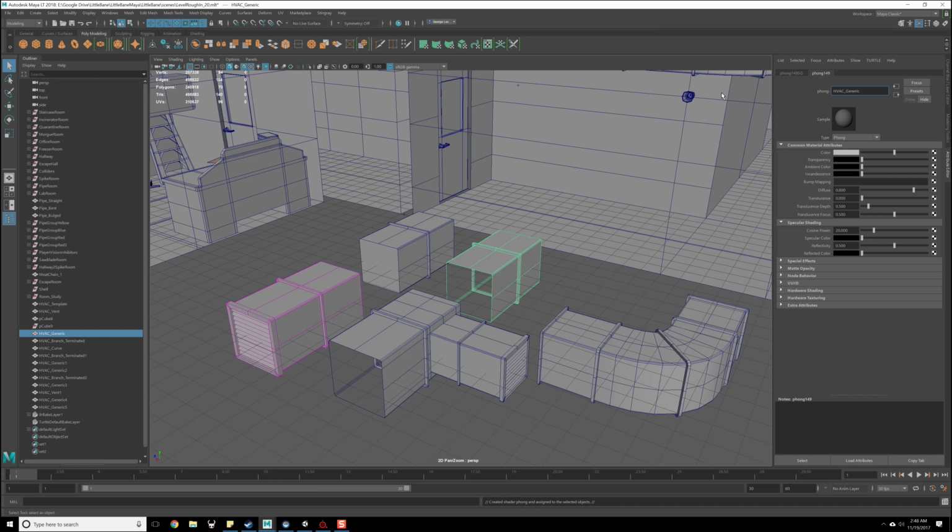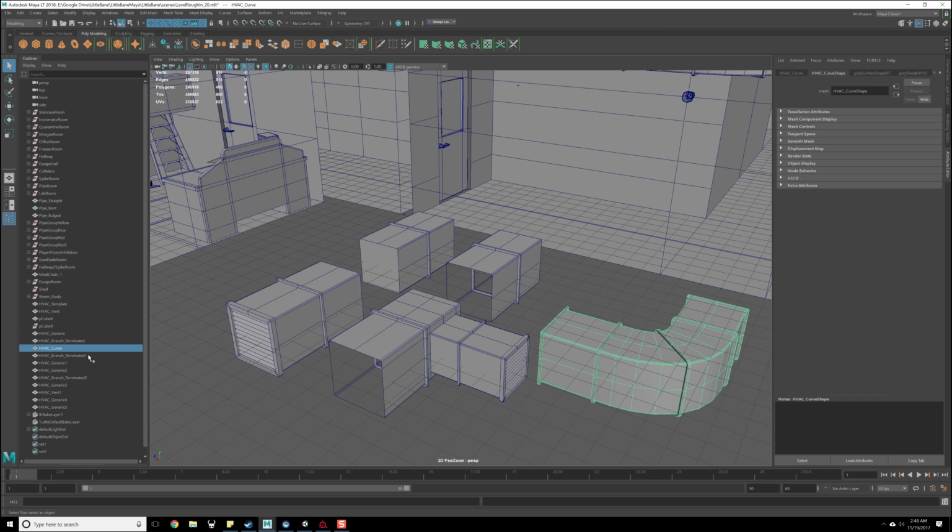Control V, underscore M, enter, grab the last one, copy that name, right click, new material, Phong, same thing as before, underscore M, enter, save. Now we're going to grab everyone, just delete the history on these because there's no reason to keep any of it, and then File, Export Selection, and bring that over into, let's see, HVAC.